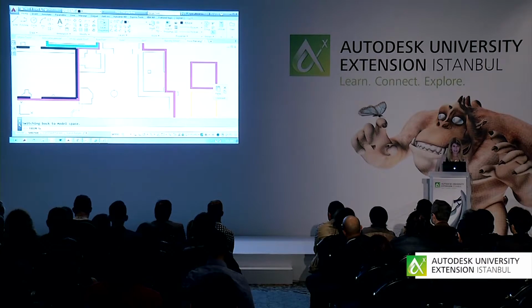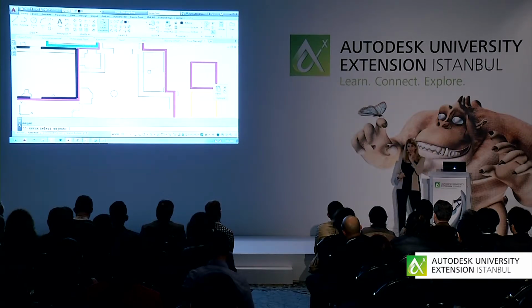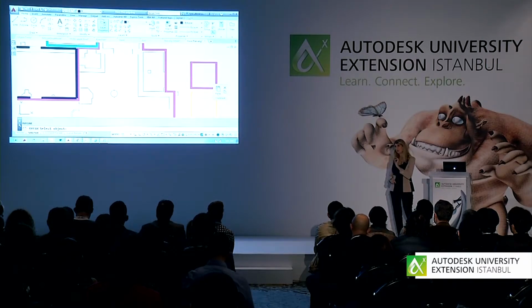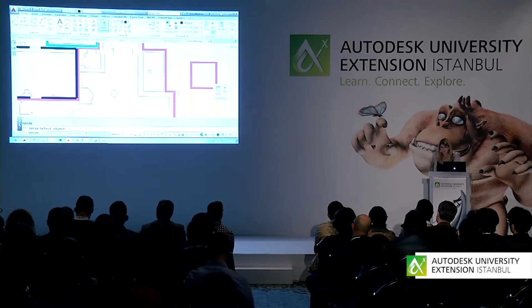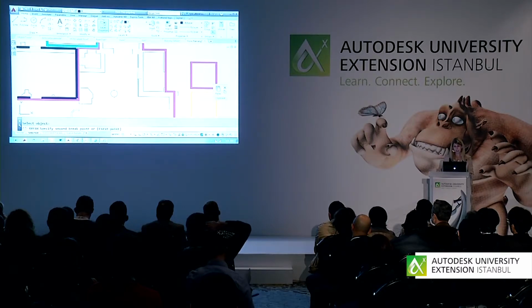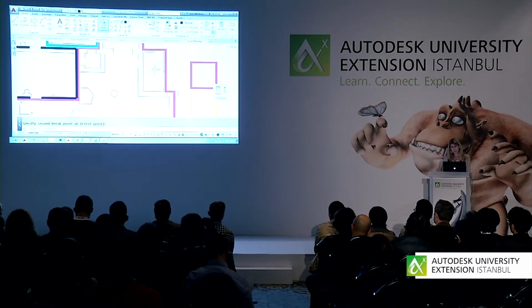Let's take a look at break. I don't know how many times you've gone into the break command, selected an object, and then forgot that the place where you select the object is the first point by which you're supposed to break it. Now it will be very obvious. I'm going to come in here and select this object to break, and look how obvious it is what's happening in the break command. If you use the break command, you will definitely appreciate that. That's the first point, and so on.